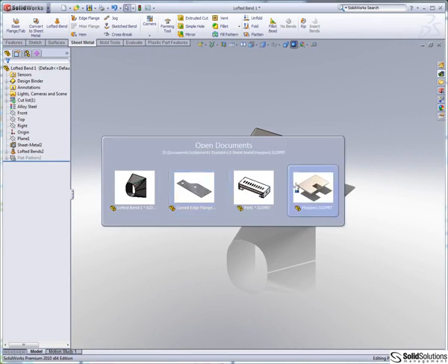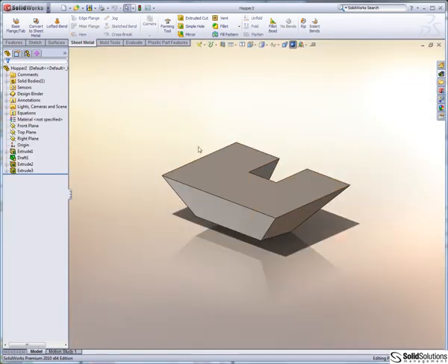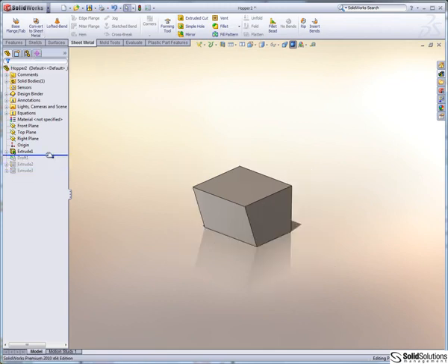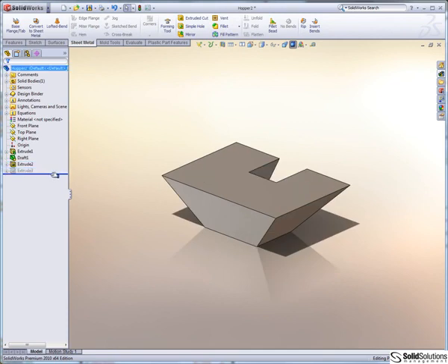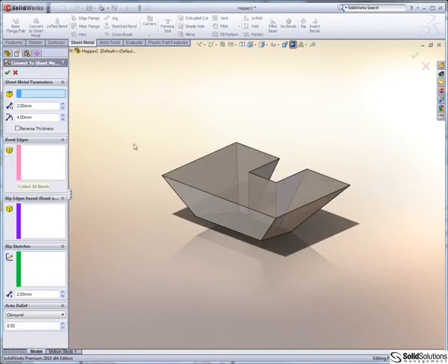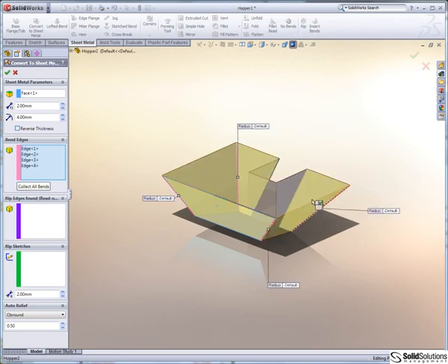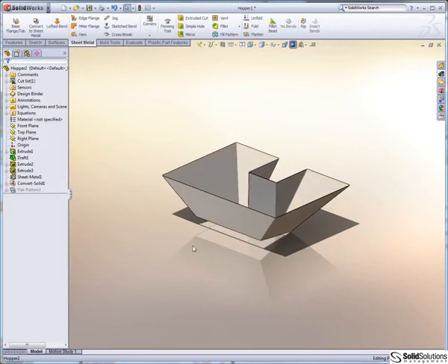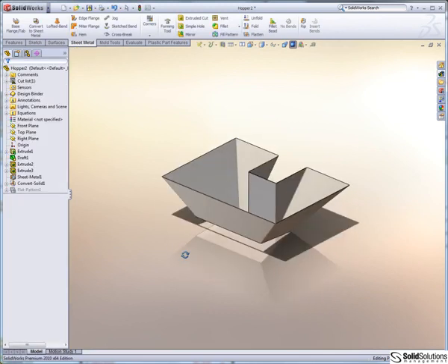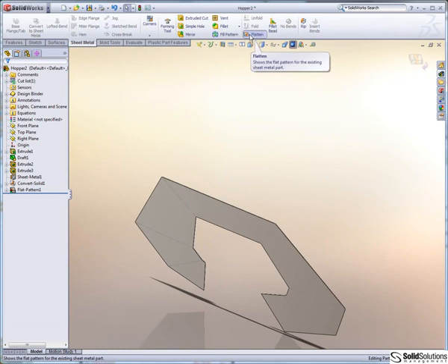Another example there is where we've got a much more complex sheet metal part, and we've just modelled up the volume effectively here. So sometimes it's much easier just to sketch out the inside shape just using solids, and then we can effectively wrap sheet metal around that volume. So it gives us the exact shape, but in a really quick and easy to use fashion. Very powerful command there. And then just one button again just flattens that out.